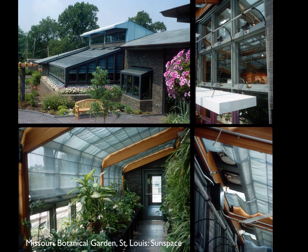So in the upper right, you can see the wall that's in between the sun space and the rooms behind it. Part of that is because it's an exhibit, so people can see into the sun space. But also there's regulating windows that can be opened manually at the bottom and in the middle. And then at the top, they're automatic because it would be too hard to reach up there. So those are switchable and they can be also put on thermostats. So that allows the convective regulation of warm air to be either cut off or circulated between the sun space and the room behind it.